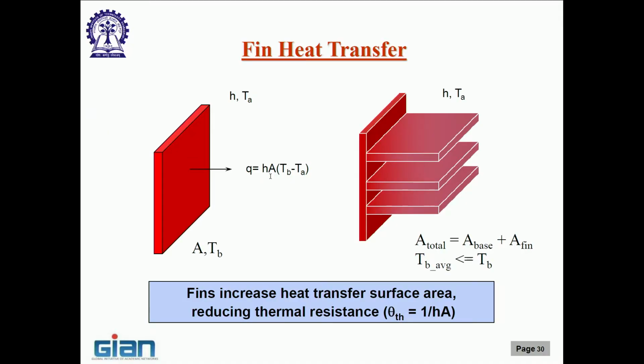Right, let me go to full screen mode. So I can increase my overall heat transfer by increasing the surface area. Now what can I do? If I have space, I can attach a few surfaces like this, appendages sticking out of this flat plate, which was originally being used to cool. That is what is called a fin. Let us say I have put 3 of these surfaces. I have made available additional surface area.